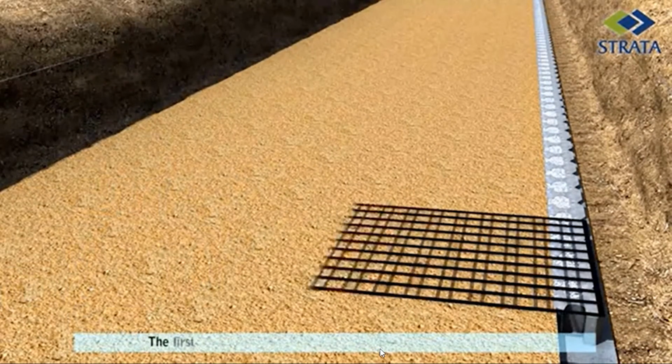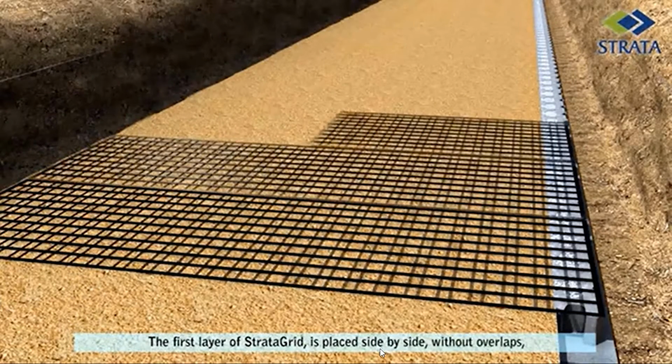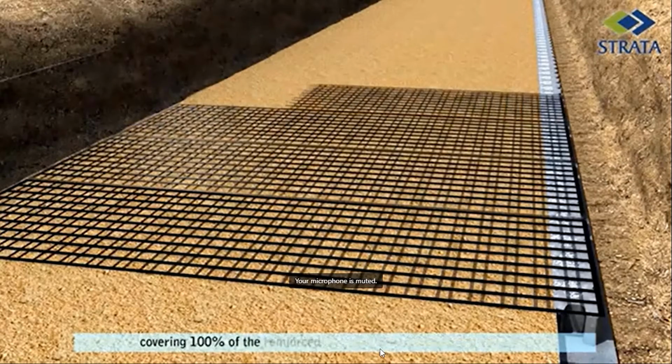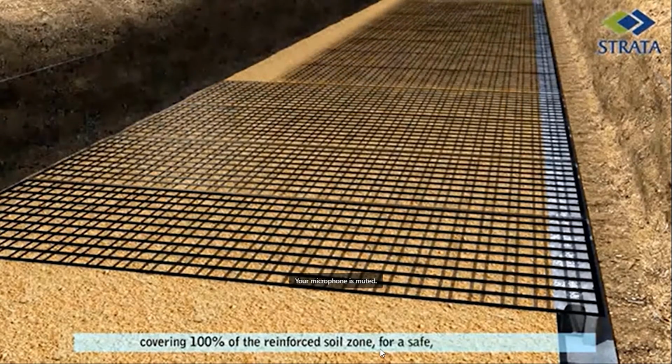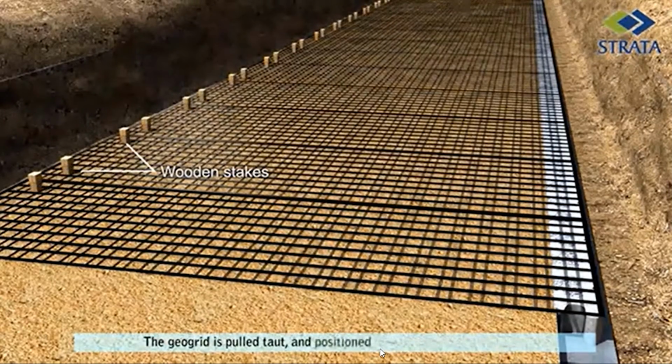The first layer of geogrid is placed side by side without overlaps, covering 100% of the reinforced soil zone for a safe and robust design. The geogrid is pulled taut and positioned in place with wooden stakes.